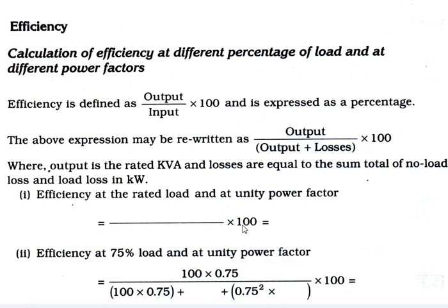We are going to calculate efficiency and all other parameters when you have completed your whole design and you are at plus 4.5% of your percentage Z. Your no load losses and load losses are within your required limits. Then you will carry on towards the other parameters, which are the efficiency, the tap calculations, errors, or whatever.